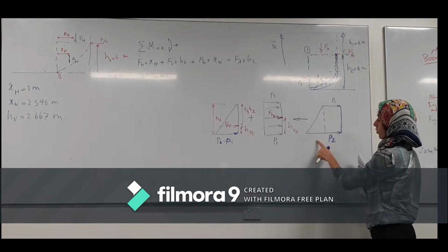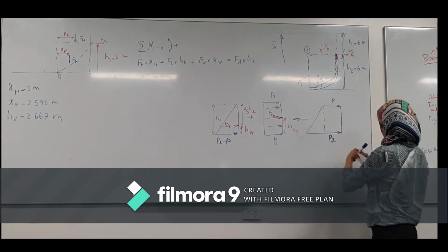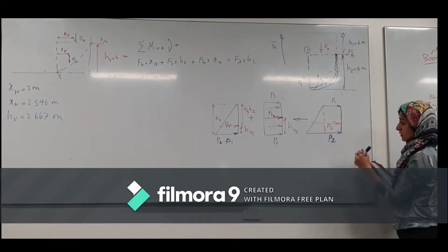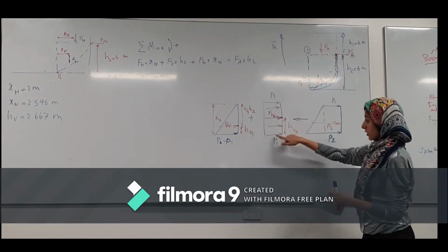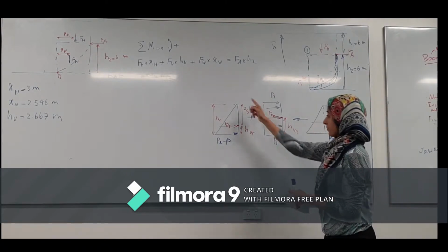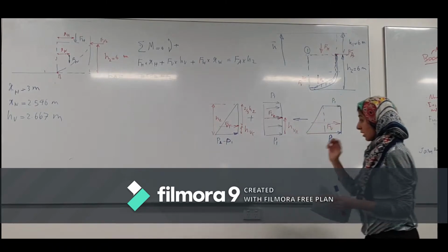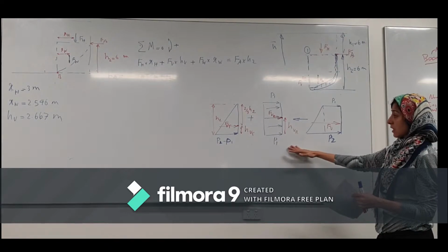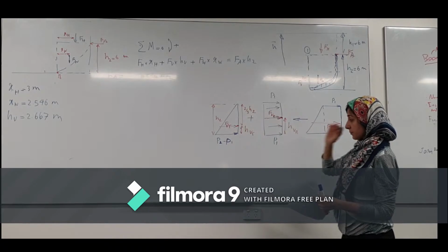But for the vertical force, we can actually say that the vertical force represents the force due to this pressure distribution. This is the same as if we consider the constant pressure, or the rectangular shape, separate from the increasing pressure, which has a triangle shape. What's the point? We do that because it makes it easier to find the location, or the center of the pressure, for each profile.